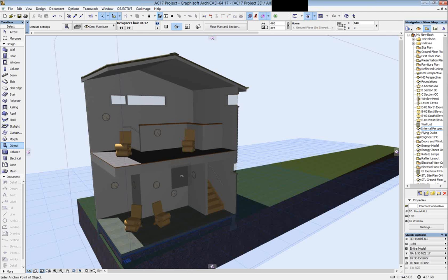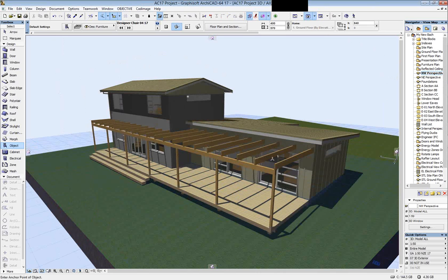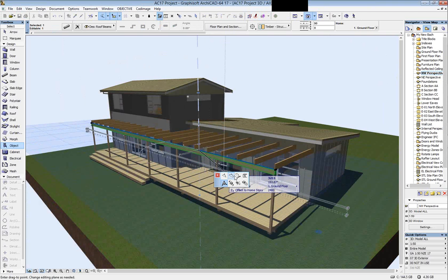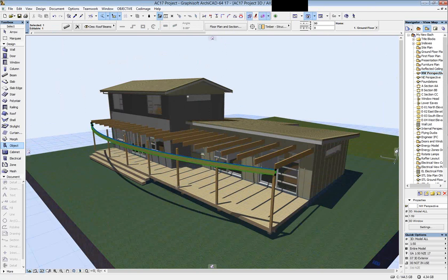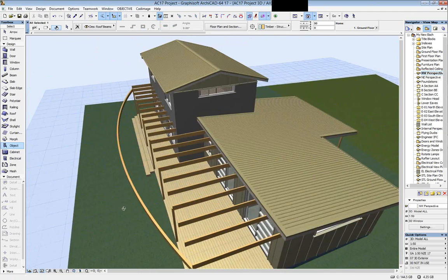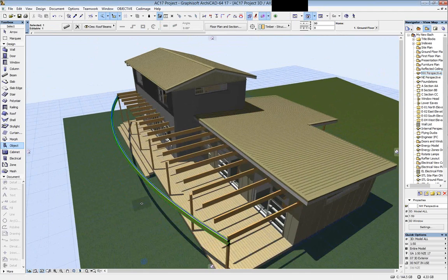A long-awaited function is the ability to curve beams. We've always had workarounds for curving rectangular beams. We could use a piece of slab, a piece of wall, whatever it was, but now we can do it natively with the beam tool. So I'm going to select a beam here, and you can see now that I've got two new functions here, curve, edge, and tangent. So choosing curve, simply curving a beam. Cool. So curving beams, you may think, whatever, I always had a workaround for that, but it's a native beam now. So if you're exporting this to your consultants, your collaborators, it is now coming up as a beam, not a wall, so you don't have to do any mucking about.